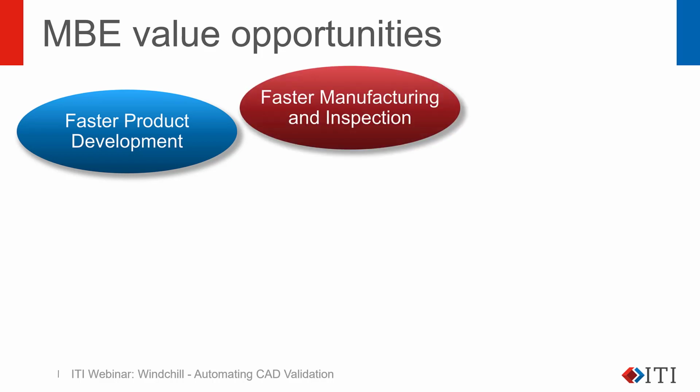3D CAD neutral file formats such as STEP AP242 and your traditional STEP files, as well as the new introduction of the Quality Information Framework Standards, or QIF, are being introduced into quality organizations to do what STEP files and 3D CAD files did for manufacturing and CNC programming for decades, to now automate in metrology and quality applications.